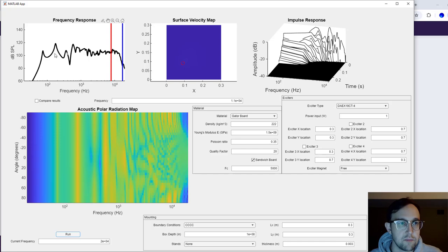So, okay, one thing to notice immediately is that the sensitivity of this speaker is very high because it's so light. And I know from personal experience that even just 1 watt into these sandwich board materials is pretty loud. So this might be a little inflated. Maybe it's like 105 dB sensitivity. That seems maybe a bit high to me, for 1 watt at 1 meter, but I don't know. Again, that's based on measurements that I took off the data sheet for how much force this is going to put out at 1 watt. So I'll have to go into my lab and confirm that at some point.